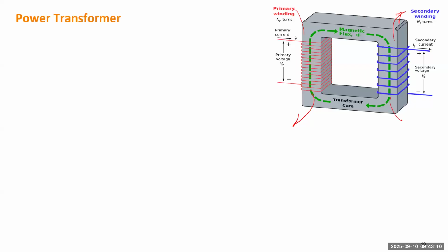So we also need to model that, and also the winding may have some resistance, so that can generate some power loss, and there could be some eddy current because of the change of the electromagnetic field, and the eddy current will generate some heat, and that also needs to be modeled. Okay.